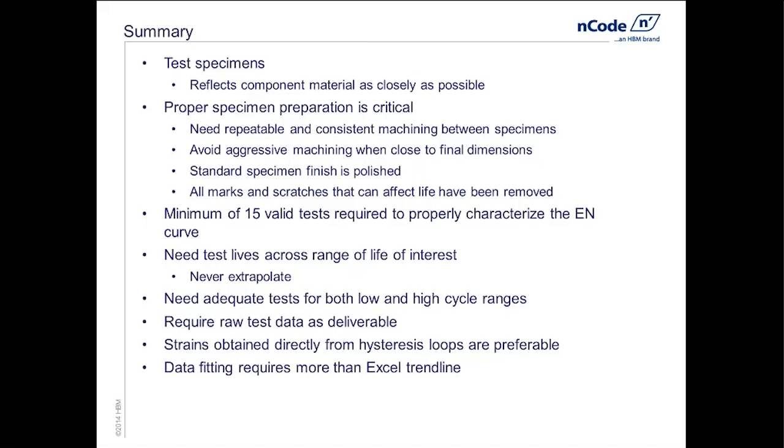One thing, if you're having this test done at an outside lab, you want to require that you get access to the raw data. For each test, you want as much data as they've computed. At the minimum, that would be stress, total strain, and life.